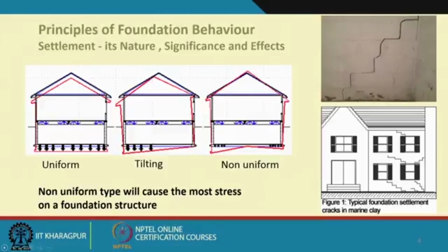And as you can see, if you study the nature of the cracks, the cracks will tell you what the problem is. In this case, there is a step-like crack, which generally indicates a typical foundation settlement crack. It also depends on the foundation and the clay, which are all very important factors. One has to understand what the factor is that is causing that settlement and the crack.